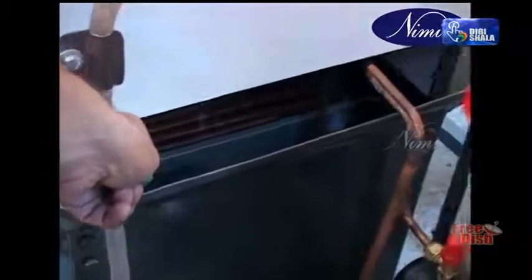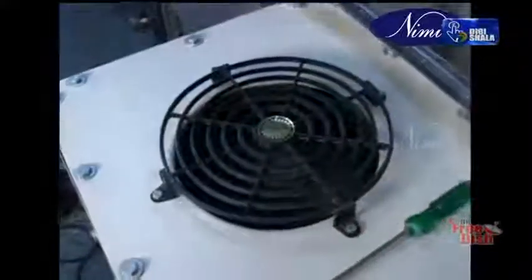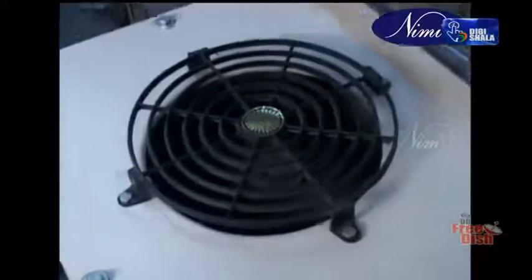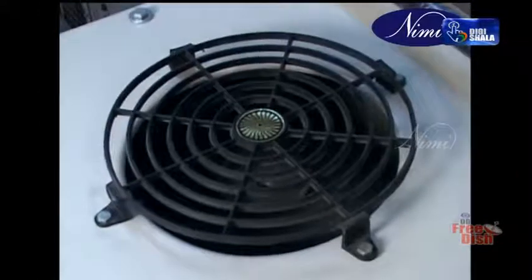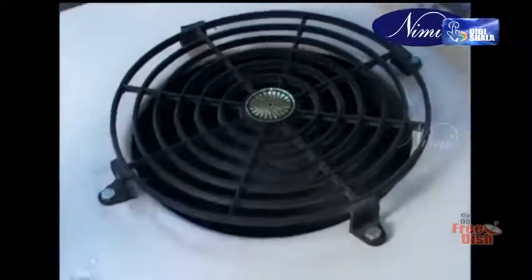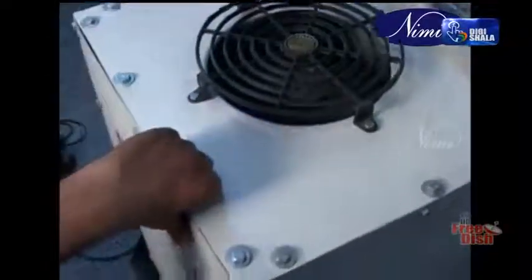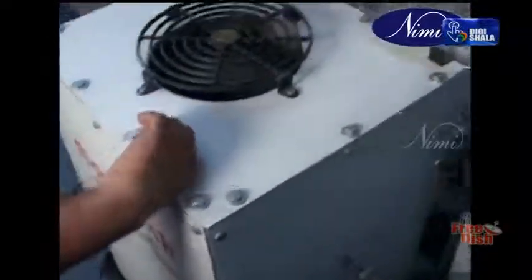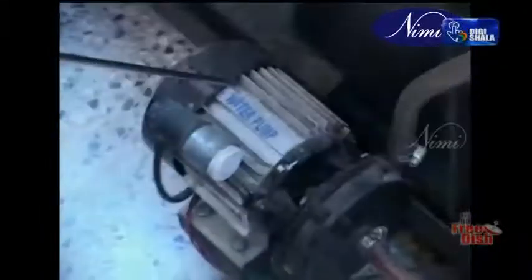Evaporative condenser uses both air and water as a condensing medium, with water sprinkled over the condenser coil. A fan installed on the top sucks the air from the bottom side. The air-water mixture absorbs the heat that results in liquefaction of the refrigerant. Water circulating pump regulates the water cycle.